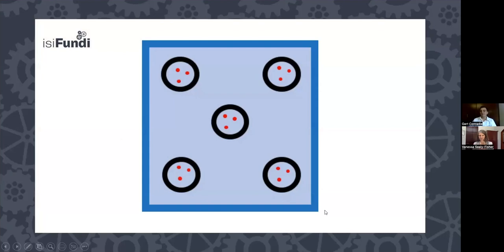How many do we take? Where do we take them? How do we know we're doing it right? PA2 has a standard method that you measure it again. What you're seeing there on your screen now is a representation of a page that is found in the SSPC PA2 standard. The blue outline that you see on the outside is a reference area of 10 square meters. So that's 10 meters by 10 meters. Each black spot that you see on there is a 4 centimeter circle in which the red dots is a